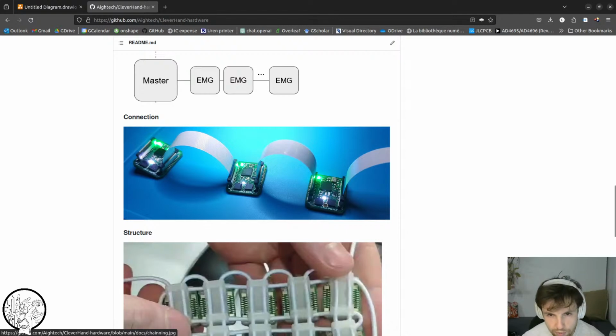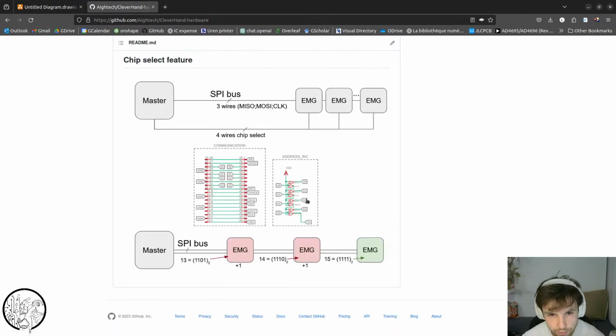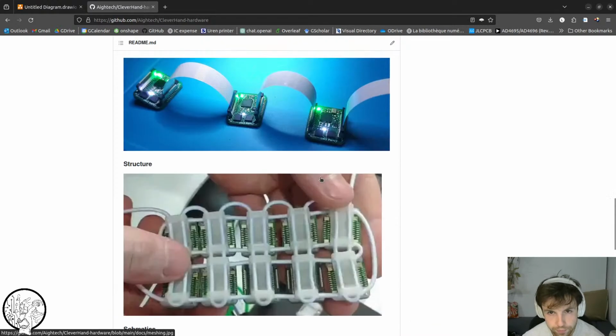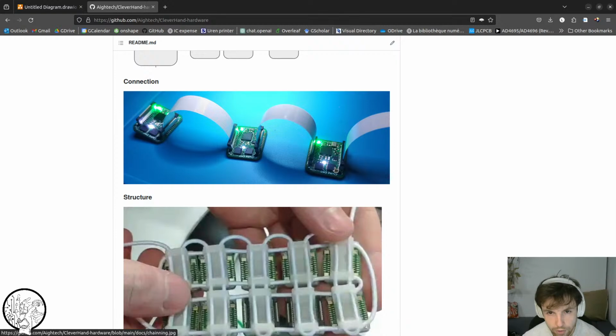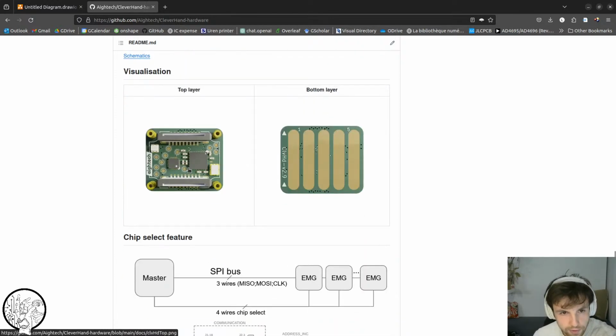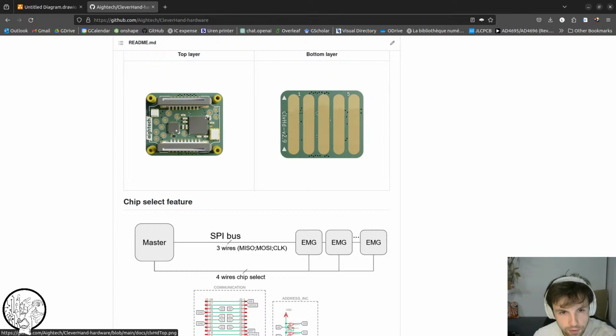And actually, you need 3 chips. This one for the NAND gate, this one for the NOR gate, and this one for the simple AND or something like this. So I was trying to think of another solution to reduce the space. I came up with the idea of, instead of doing it in a hardware way, why not use directly a microcontroller?